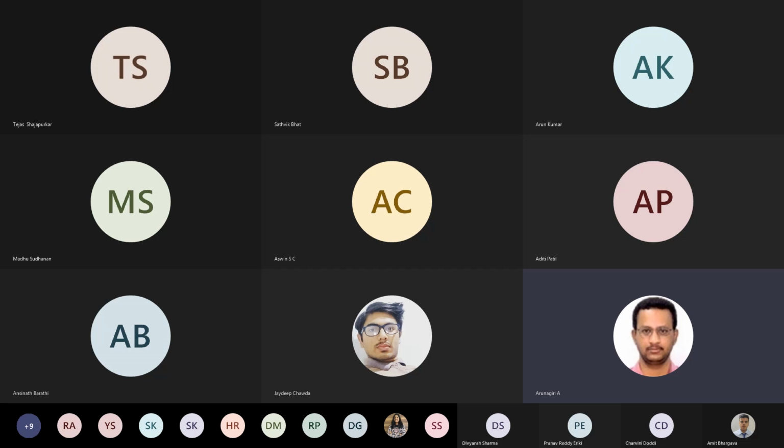The very basic methods, developed before the 1960s, were designed without considering bypass and leakage. In an exchanger we have so many streams. In ideal cases we can see ideal cross flow and ideal axial flow. But practically that is not the case, as we have many bypass streams and leakage streams.